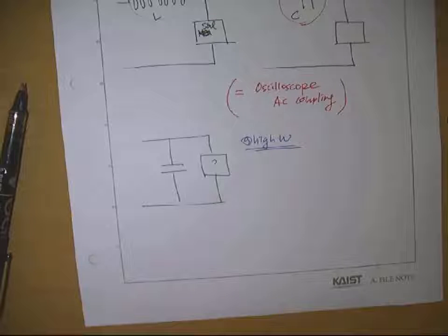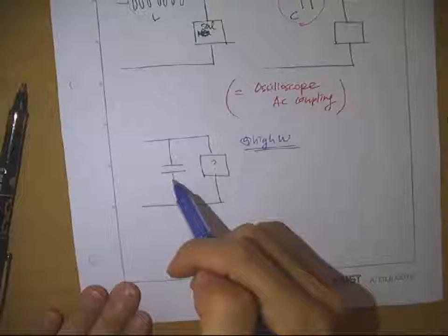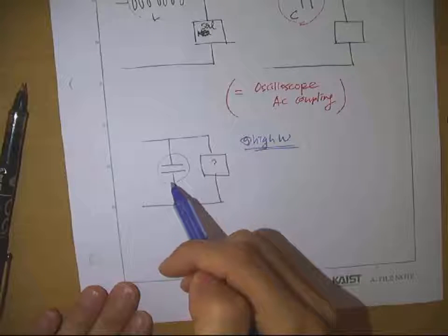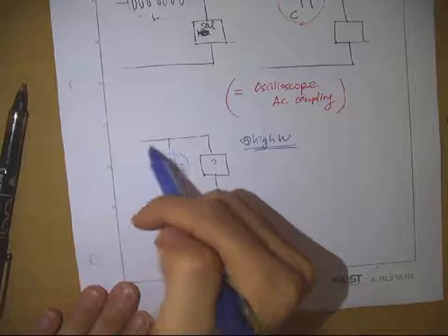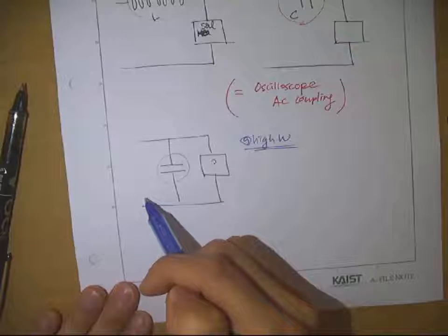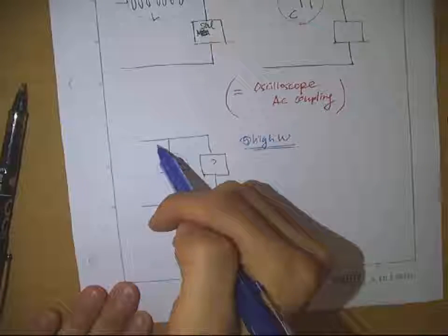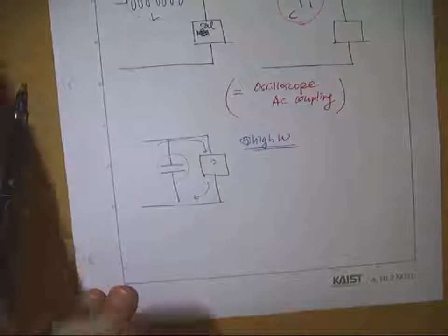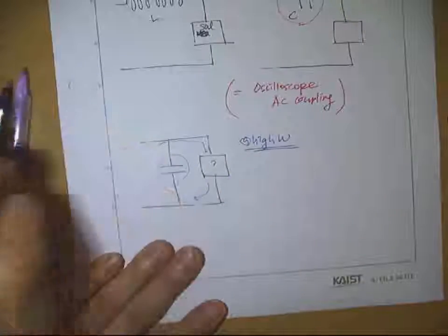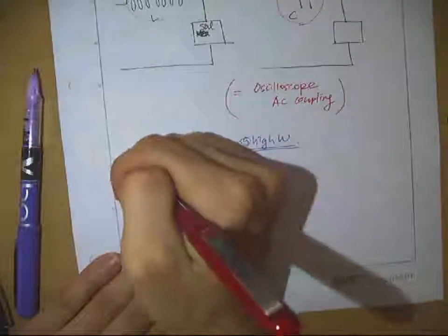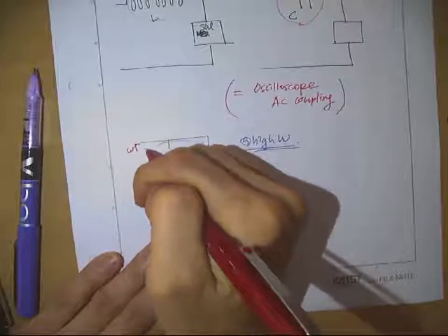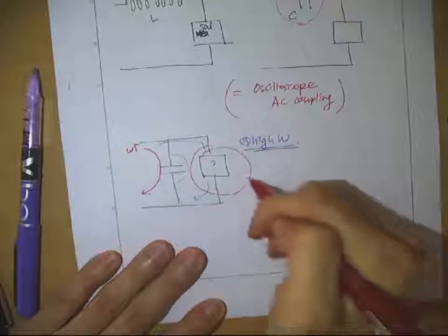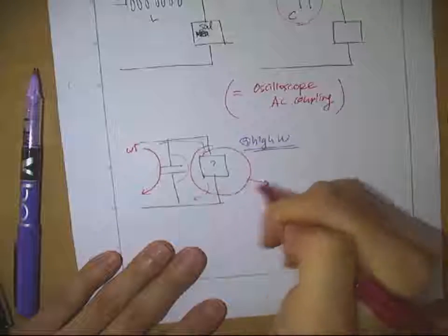If you think about the impedance of this one, it will go to almost zero, so that there's a free way for charges to move. So charge wouldn't go here. As the frequency increases, current will flow in this direction, and this part will feel like it has disappeared.